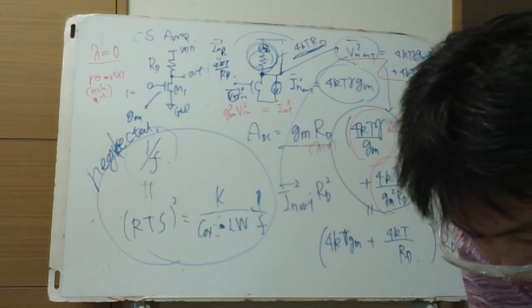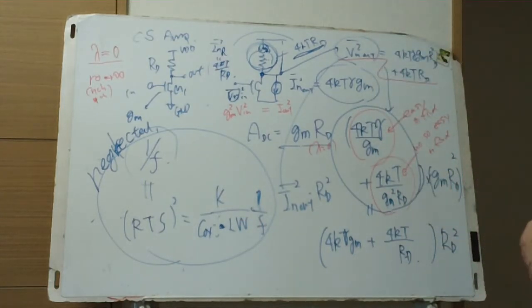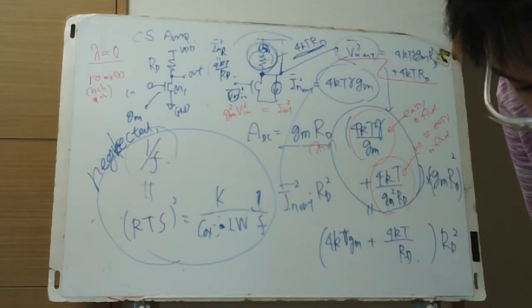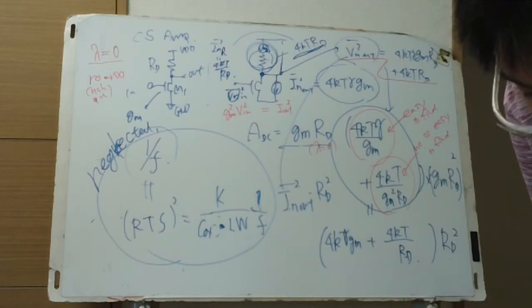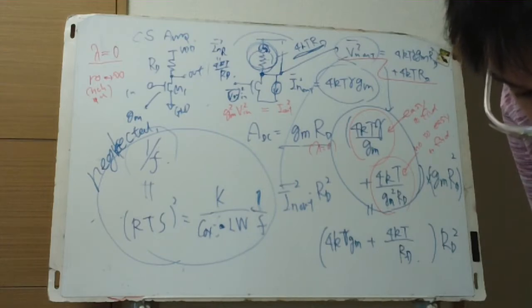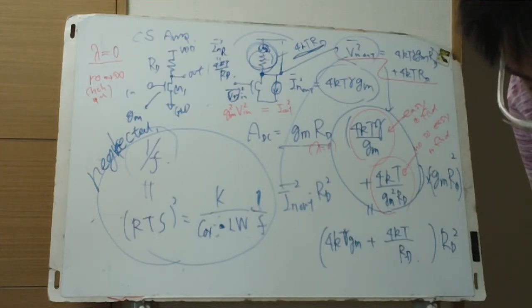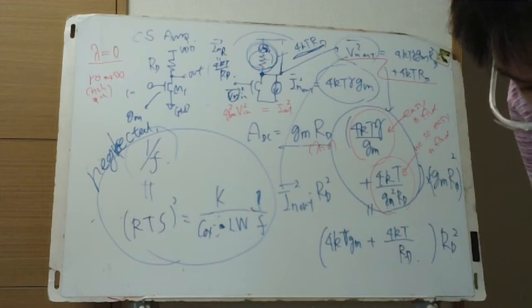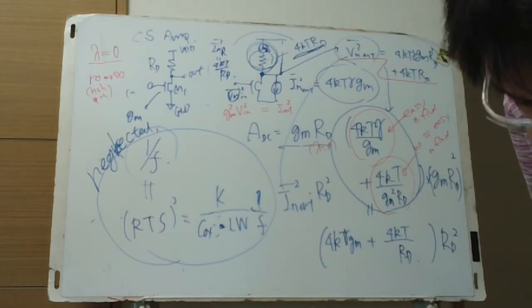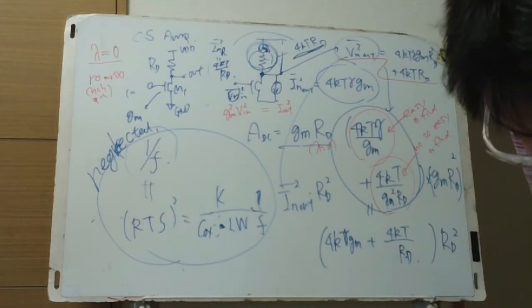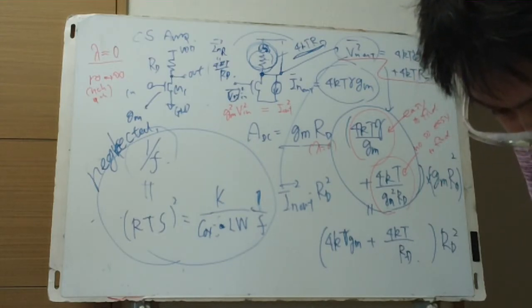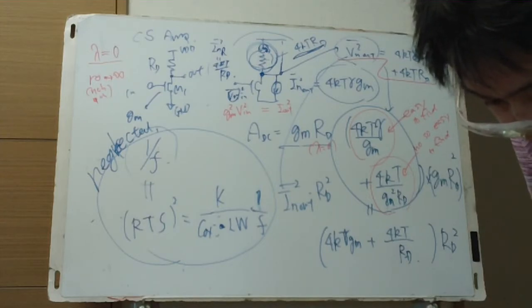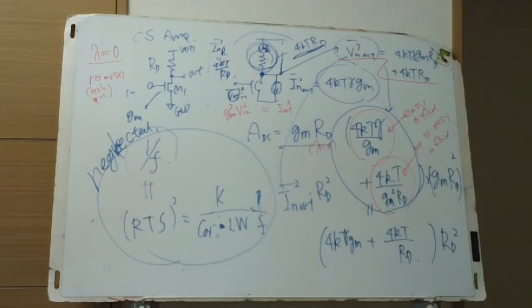Each of these current sources has its transfer function. Note that the noise mechanisms add as power quantities because they are uncorrelated, given by this formula, which represents the noise power per hertz at frequency f. The total output noise is obtained by integration.